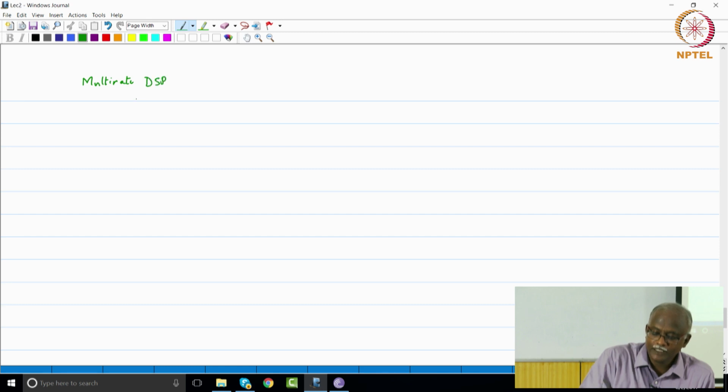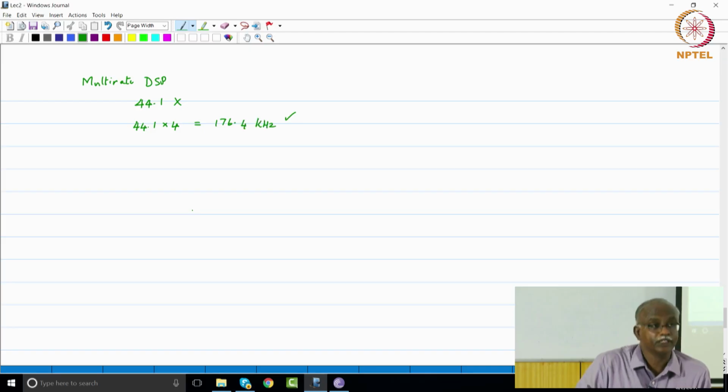Let me just give you an insight, and then we will pick it up from here. Multirate technique, in fact all your CD players actually use this. Multirate DSP says, hey, 44.1, don't do that. Instead do 44.1 times 4, that is 176.4 kilohertz sampling. Okay, do this.